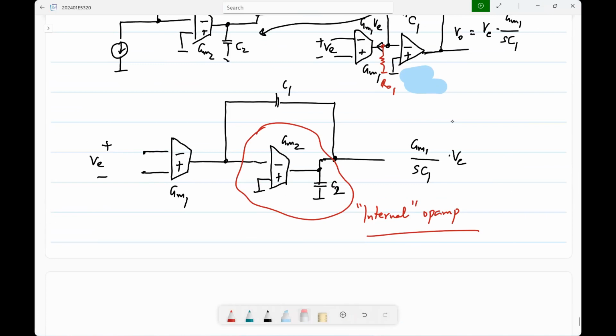Right. Exactly. So the gain of the second stage helps you, right? So the second stage also has a gain. So that's another way to think about it. This output voltage doesn't appear across RO1. Some fraction of that appears across RO1. So the current that you have to drive from GM1 is much smaller. So that means the input error voltage is much smaller. Which basically makes the virtual short better. Okay.